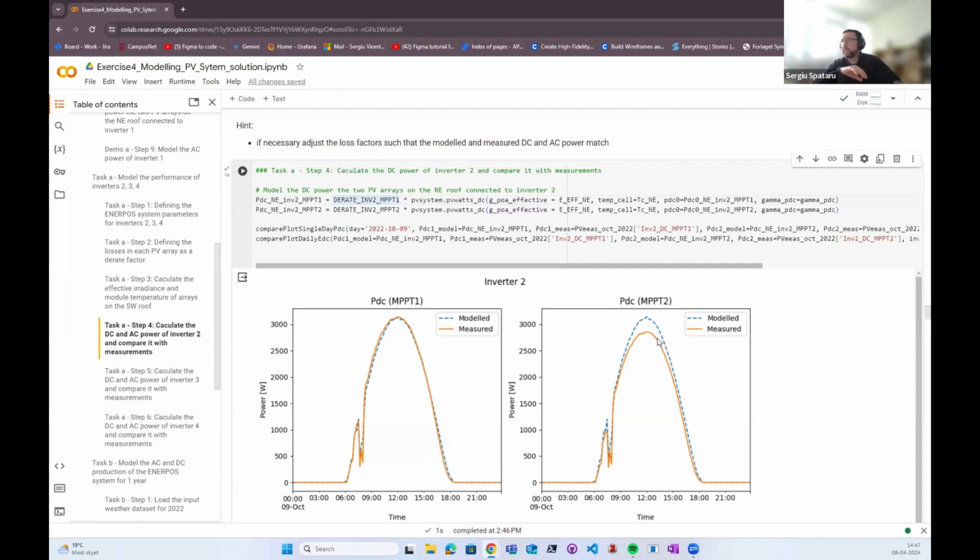So unless I go there and see specifically what's happening with the system, I cannot know. The only thing I see is the degradation is uniform, or the reduction in power is uniform. It's not a shading kind of thing. So what can I do for this one? It's basically the rated capacity of the entire string has been reduced.